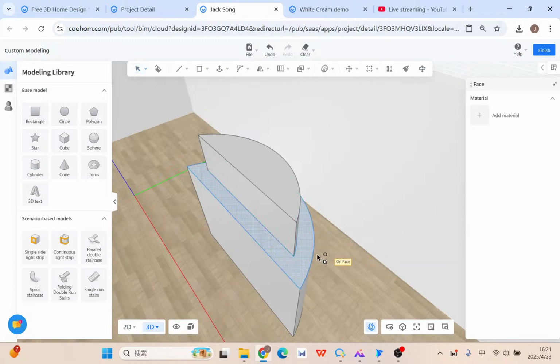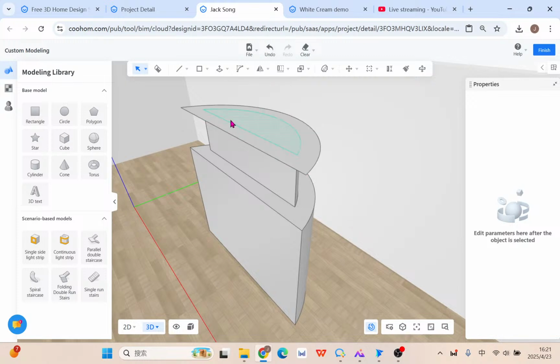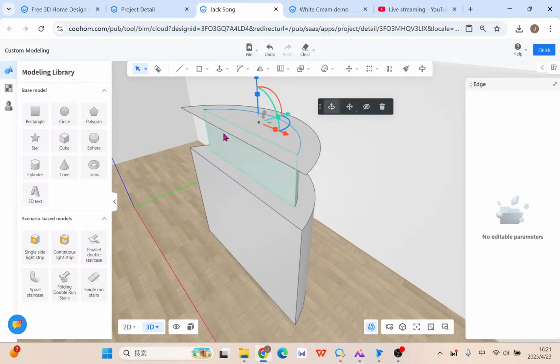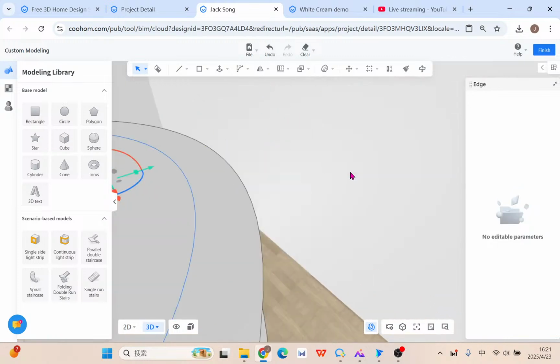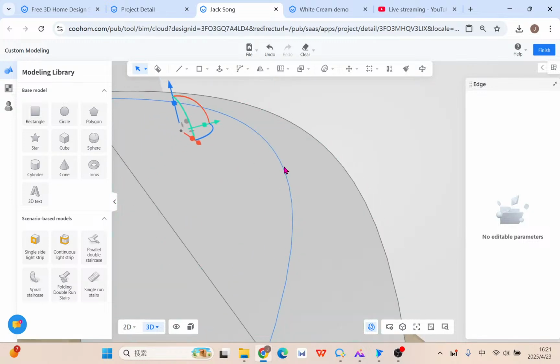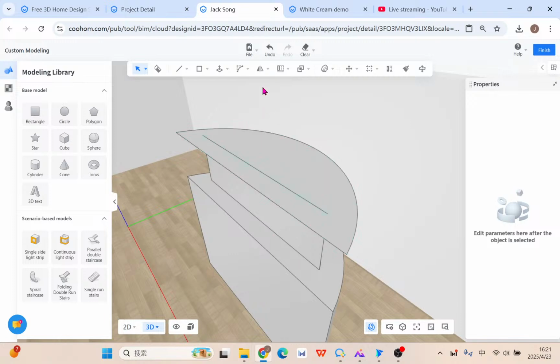For example, duplicate one point, two points, and now you see the new surface combined, and here you can click the line and delete it. When there are two surfaces, you get two different regions that share exactly the same line, the connection.